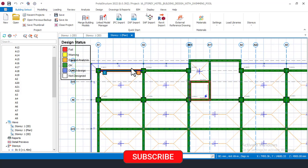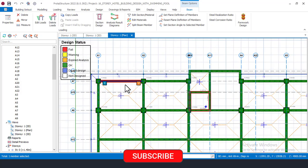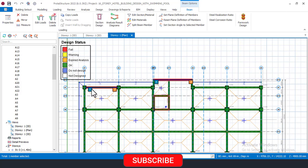When you're doing your beam interactive design, even if your beam is showing green or red or anything, you must check the beam to see the kind of bar that was used. It's very important for you to check the beams. Right now, come here and click on this beam. I have checked all the beams on this line, which is these two beams here. So I can choose to start from here, so that I will not miss any. I'll deal with all the horizontal beams first, and then the vertical ones.